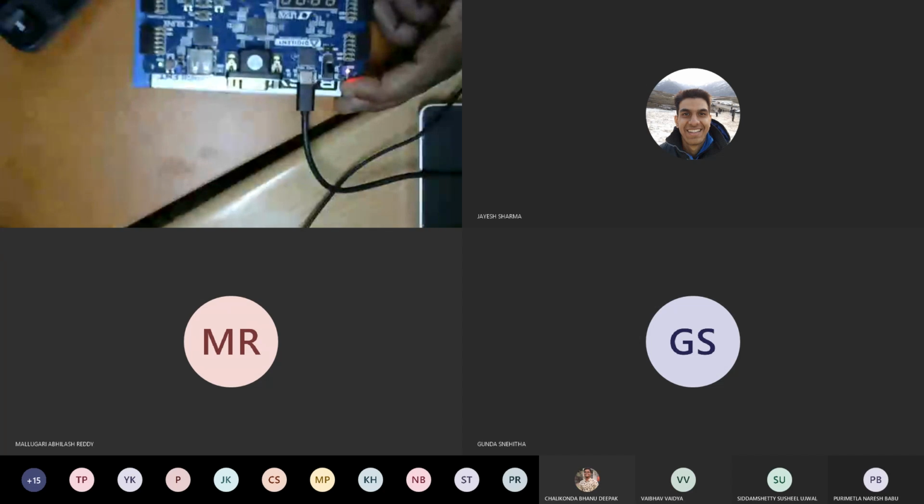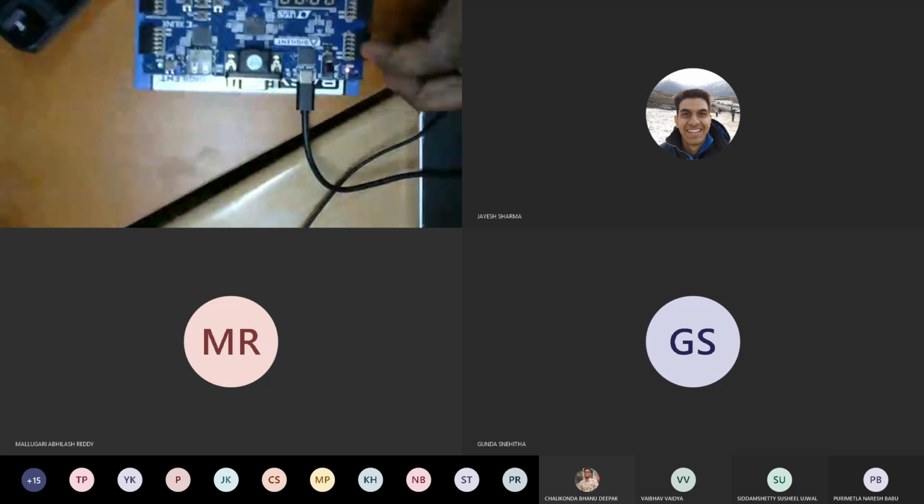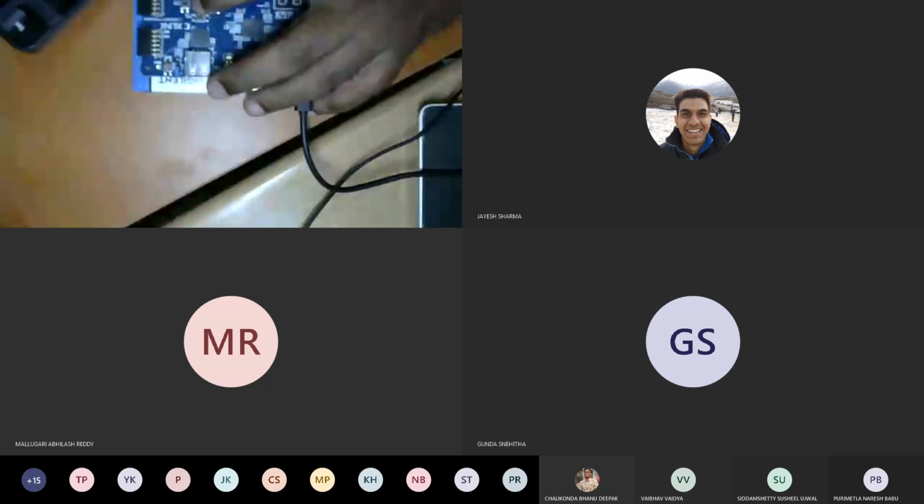So now see here, my reset equal to 0, right? Reset equal to 0, and my Q bar is glowing, Q is 0. So now even if I change J, K, nothing is happening. Of course, it's because reset is 0, and of course the clock is 0. If I give the clock, with reset equal to 0, nothing will happen.